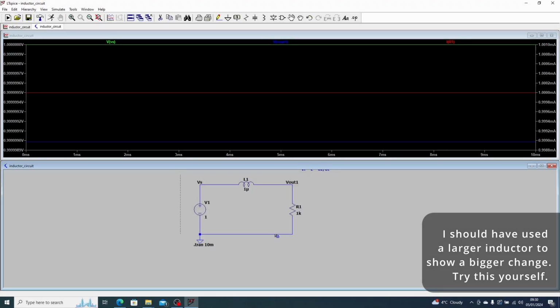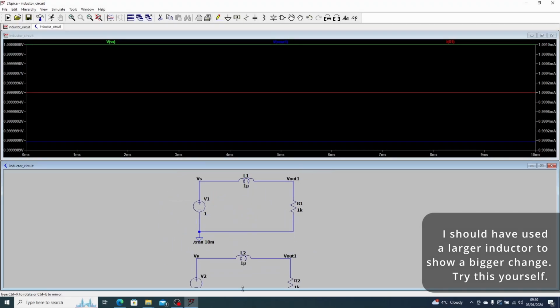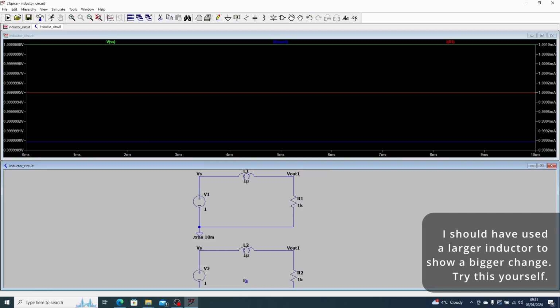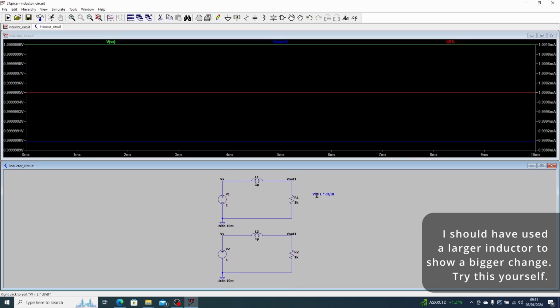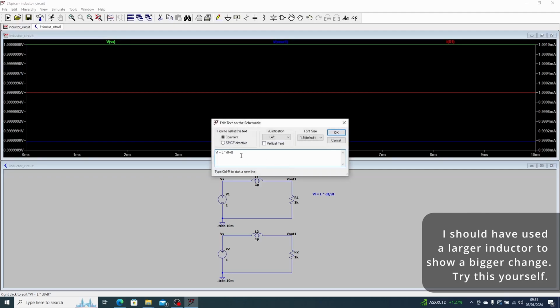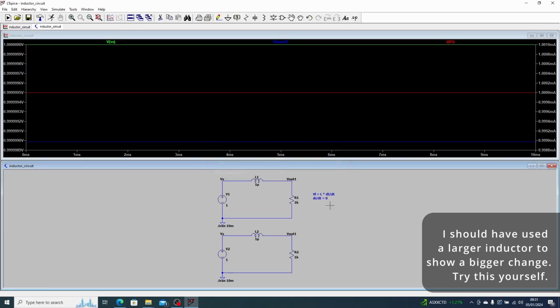Now let's see what happens if we introduce an AC current, so a voltage source which has a change in current. So for the first part of the circuit, our di by dt value is equal to 0, as our current is not changing. So if the di by dt value is 0, that means that all of this is 0. That means the voltage across the inductor in an ideal case would also be equal to 0.